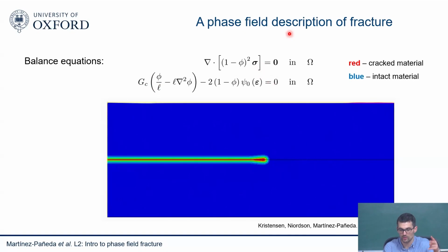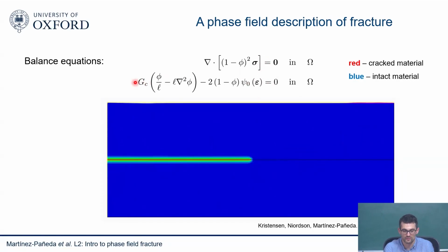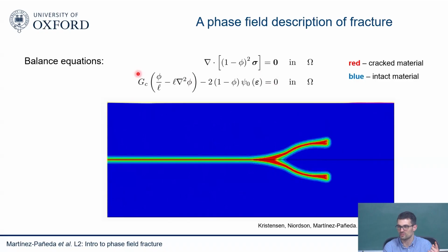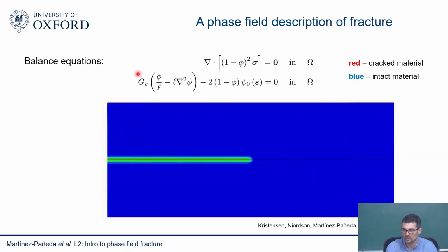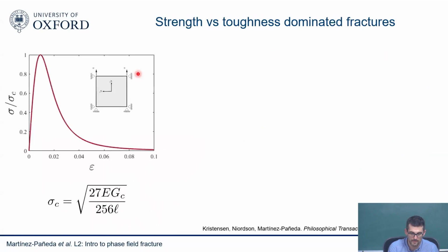So that's the benefit. You're solving independently, so that has some computational advantages. And then the other one is that you only rely on one parameter that has a clear physical meaning that you know from a fracture test, and you connect damage and fracture mechanics very well. I think those are the key advantages versus non-local continuum damage mechanics. Okay, so there's one aspect.